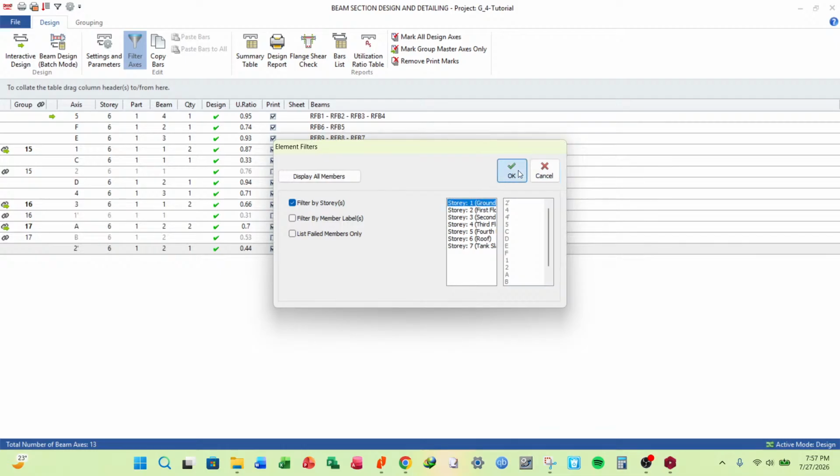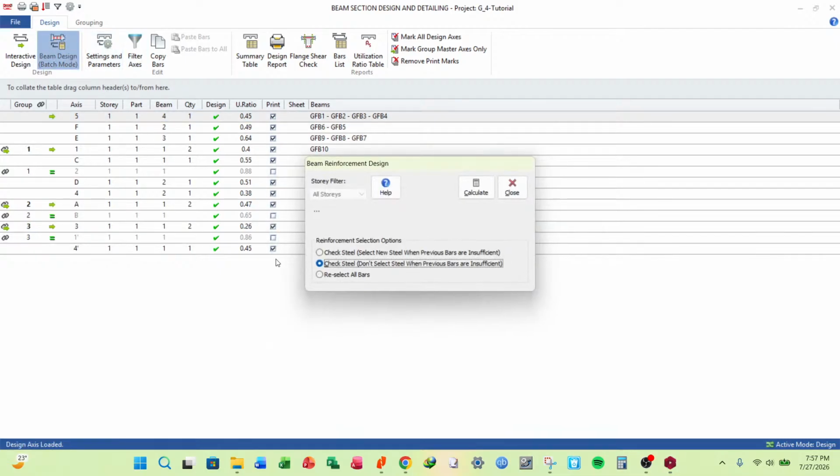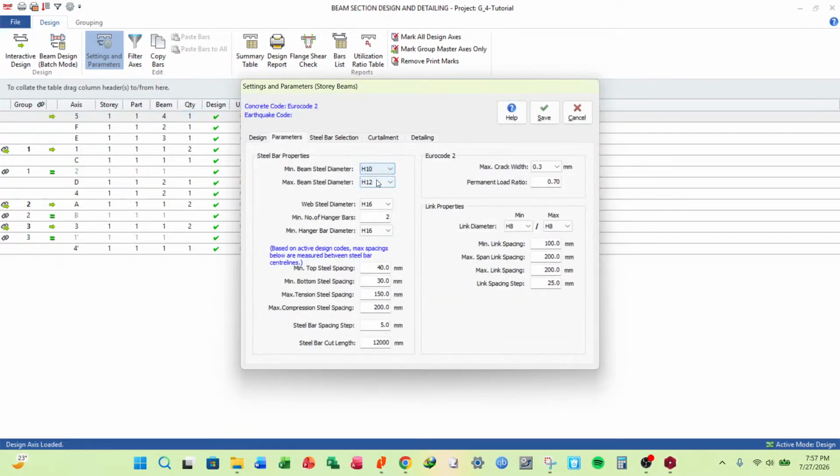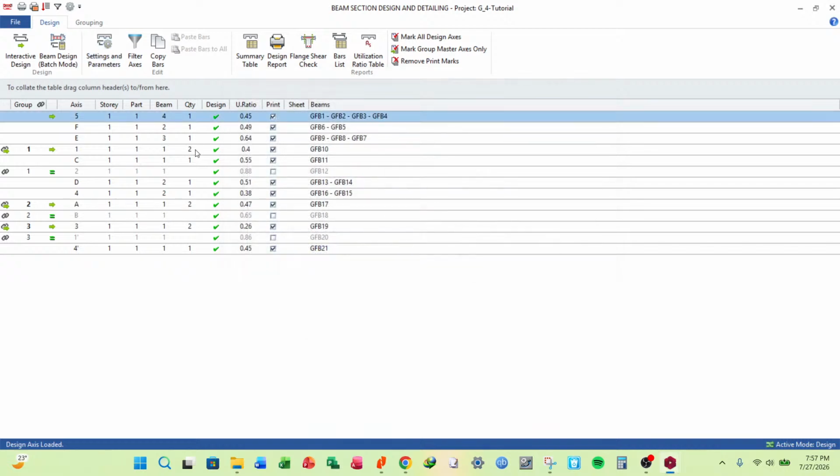Then let's go to the ground floor level. Let's redesign it with 10s. T10. So our soils are not that bad. Our ground floor beams will rest on plinth walls which are stiff enough, and they rest on firm soil, so they are stiff enough to resist all deflections at this level.